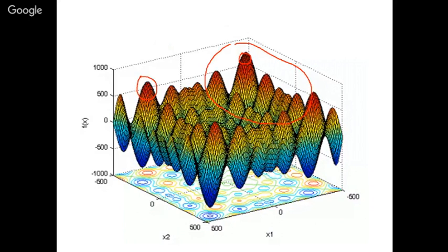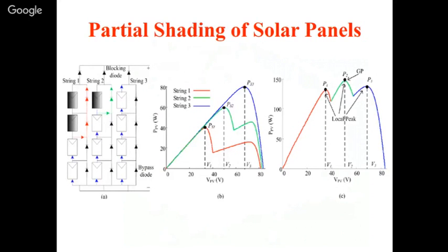In order to get the multiple peaks, and those multiple peaks also, say in case of our PV, how it is, that is what we are going to see. So in PV, when there is some partial shading, when you have the partial shading effect, these multiple peaks will come. Say you have a string of PVs connected. Mostly, according to a voltage and current rating, not only one module, we'll connect a string of elements. So here, in the first string, there is no partial shading. In this string, there is no partial shading. In the second string, if you see, only one of the PVs is shaded.